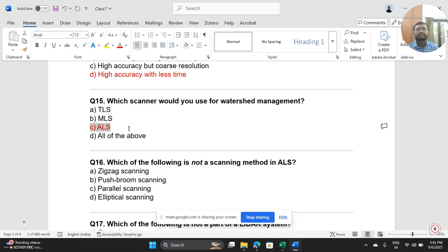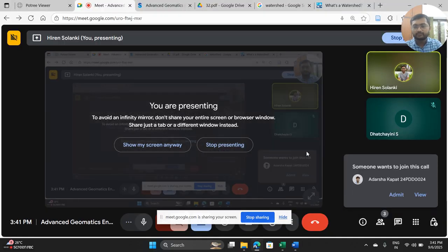Basically, if the area is very static in nature and we need high precision and detailing, then we can go for terrestrial laser scanners, where we want to monitor progress or monitor sites. ALS is for when you want to cover a larger area, such as when a smart city is coming up, or a metro line connecting two different states, or national highway construction, or you want to analyze an entire city, such as Mumbai or Surat. In that case, the airborne LiDAR system will be helpful.